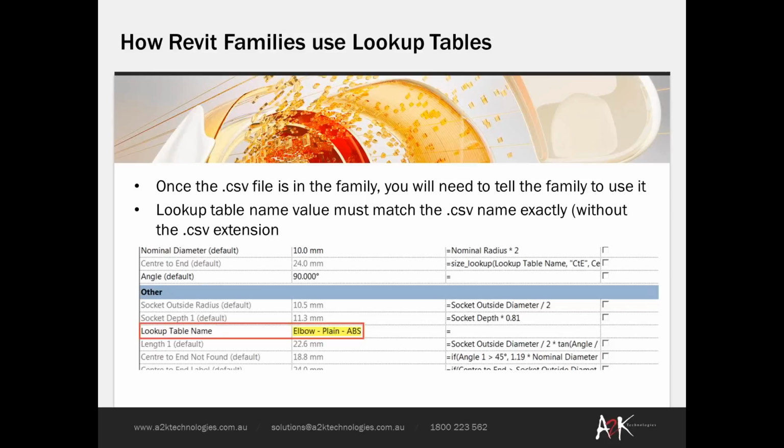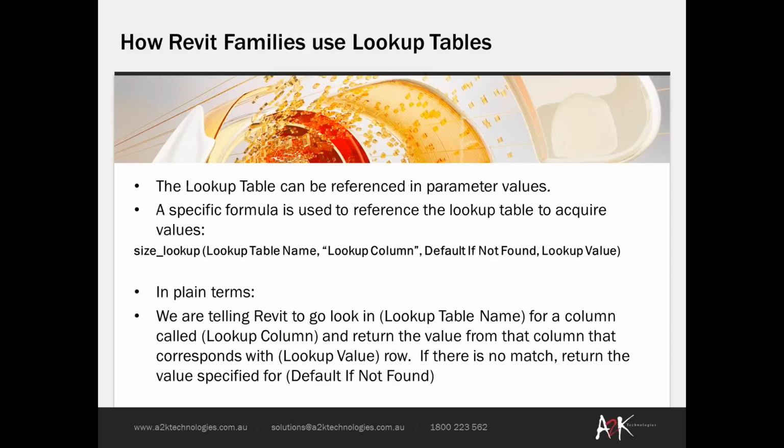Okay, so once you've got the lookup table name parameter and you're referencing the lookup table CSV file in the value of that parameter, you then need to tell the family how to use it. So let's have a look at how that formula actually works.